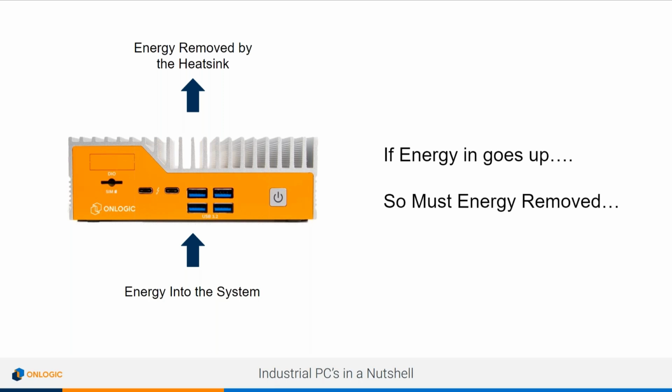There are higher and higher current requirements on M.2 and all sorts of motherboard expansion that must be considered. And on top of that, there's also efficiency loss on capacitors, all sorts of chipsets and LAN controllers that must also be kept under critical temperatures for our regulatory requirements.